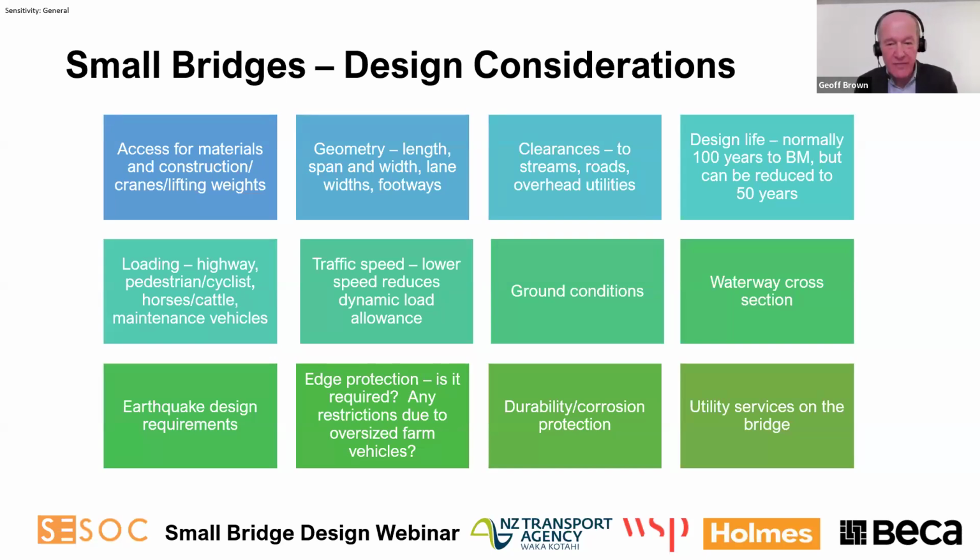What are the ground conditions at the site? What waterway cross-section do you need to suit the waterway? What are the earthquake design requirements? What is the edge protection? Is it required? Are there any restrictions due to oversized farm vehicles? What are the durability corrosion protection requirements? And is there any need for utility services on the bridge?